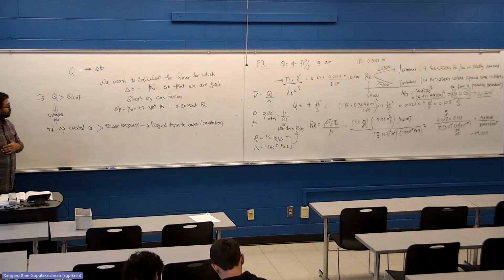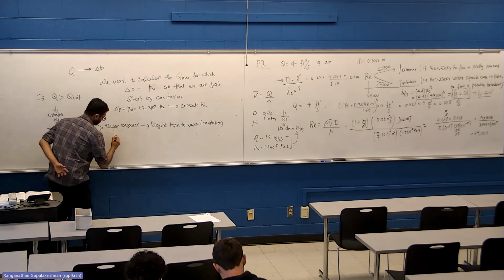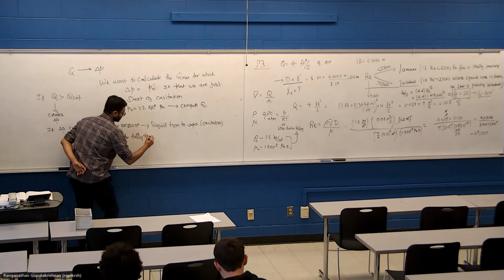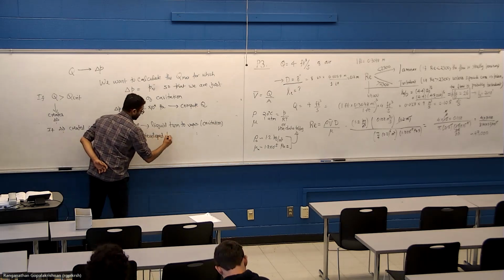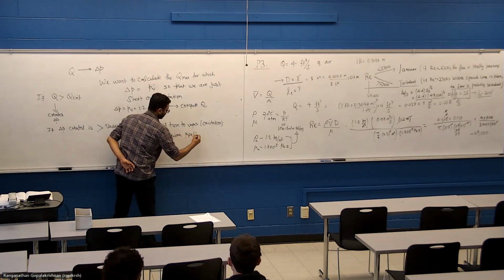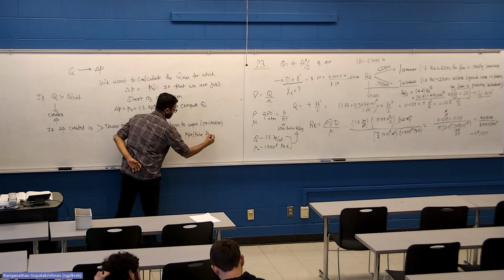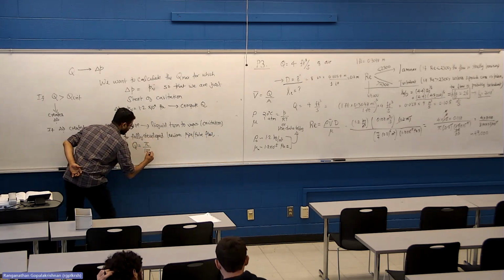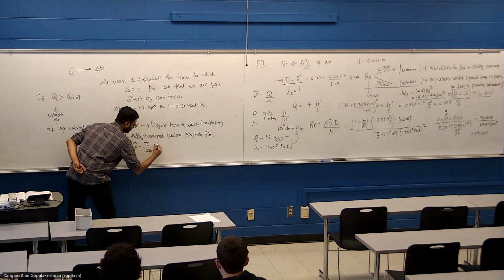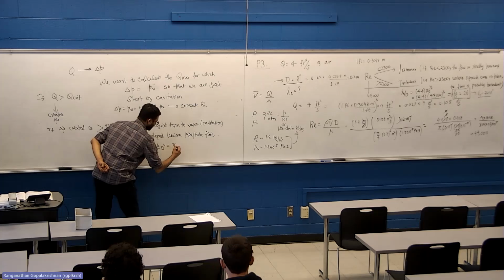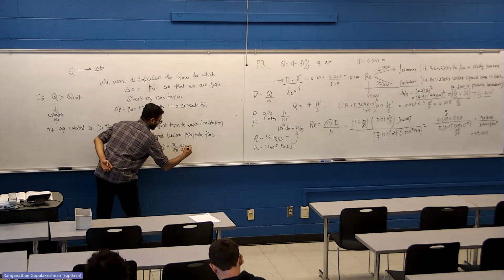For this delta P, compute Q. Okay, so Q for fully developed laminar pipe flow. Q is pi over 128 mu, delta P over L, times d to the fourth, or pi over 8 mu, delta P over L, r to the fourth.